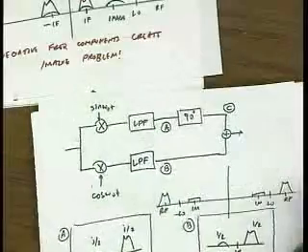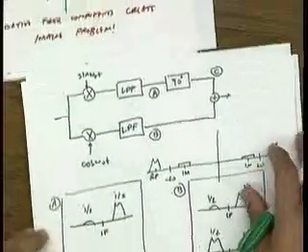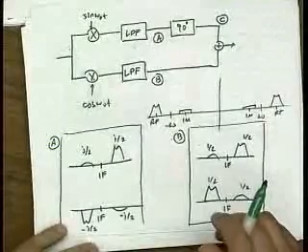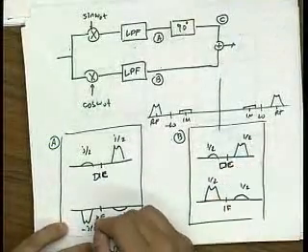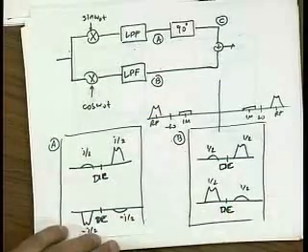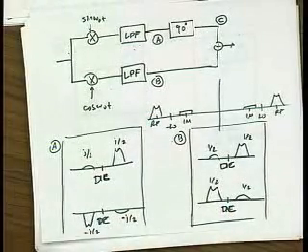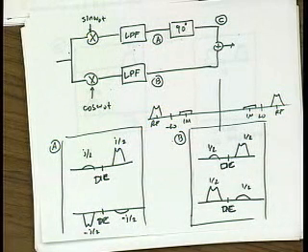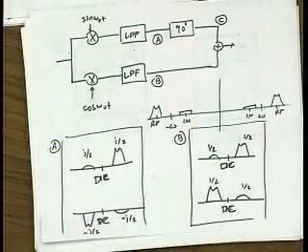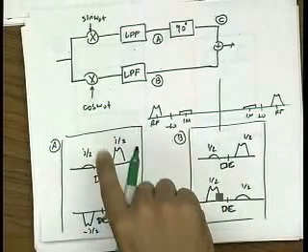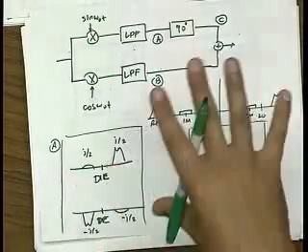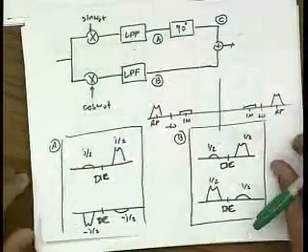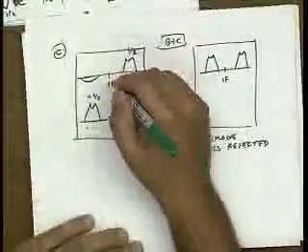Yeah, let me actually do this differently. You're right, I screwed up. Thank you. Thanks for catching that. This should be DC, actually. So this example only applies for direct conversion. Okay, at least one person's awake today. Would the IF just be the center frequency of your information? Yeah, but he's right. Because I applied the Hilbert transform, it wouldn't apply unless the frequencies were negative. You don't have to go to DC, but this particular example I just did only works for direct conversion.